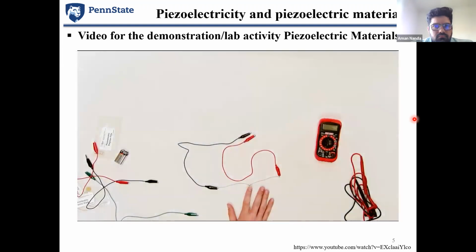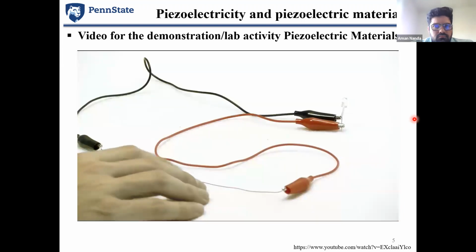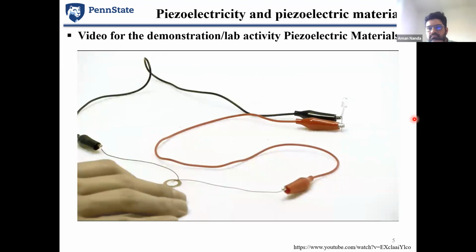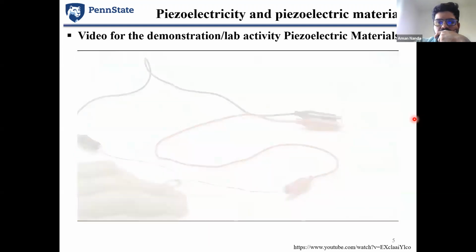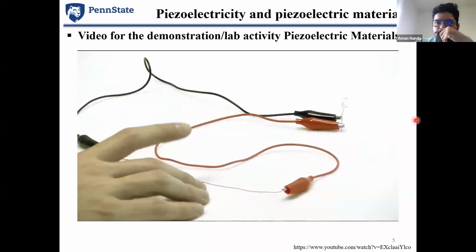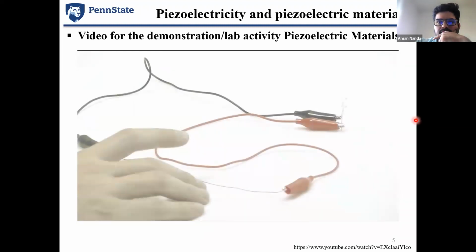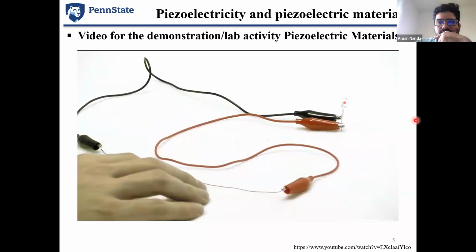With a very light tap, slowly increase the force until the LED visibly flashes with each tap. Show the effect to students. It is important to simply tap the disc and to not apply steady pressure. The room must be fairly dark to see the LED light. The LED light flash has been enhanced for this video.